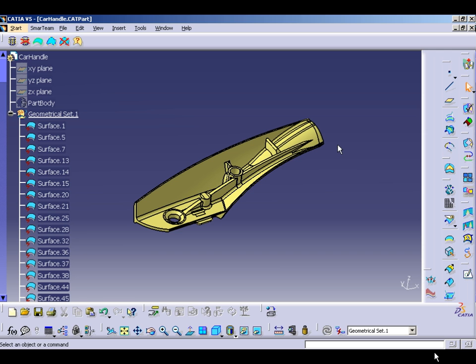The design part received by the mold designer is a plastic handle for the door of a car. This part has been designed with another system than CATIA V5 and is provided as an IGES file. The result of the IGES conversion is a set of unconnected faces.